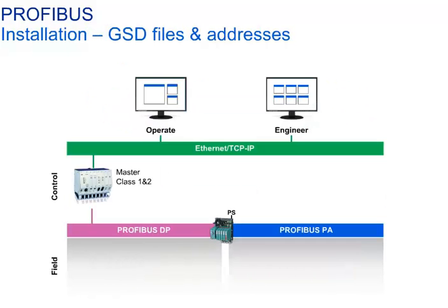Once the Profibus DP and PA network, cables, junctions, couplers, power supplies, etc. has been set up, the field devices, slaves, can be installed. When the first field device has been connected to the Profibus network, the device-specific driver file, General Station Description or GSD file of this field device is loaded into the engineering system, and a communication is established with the field device.